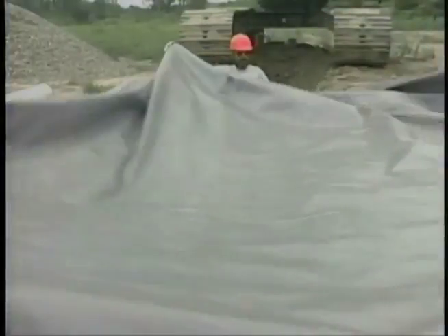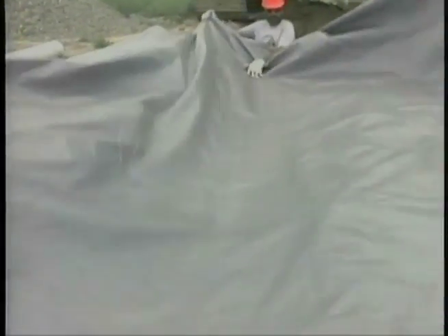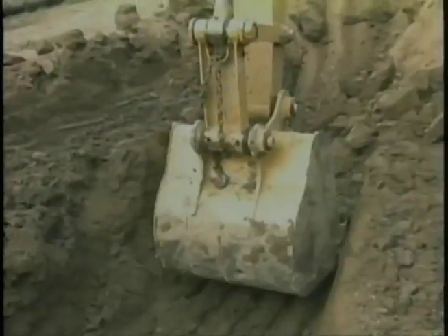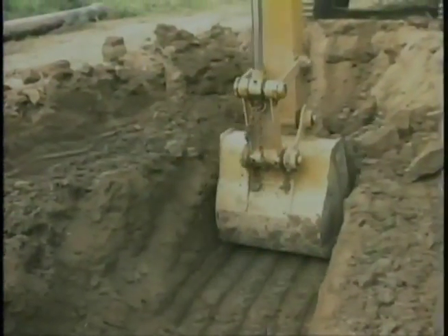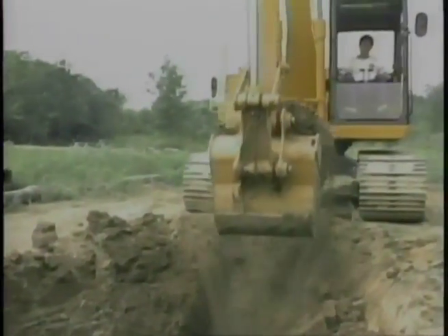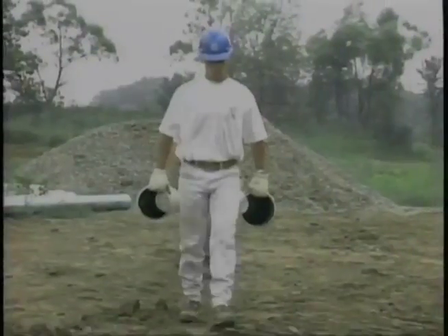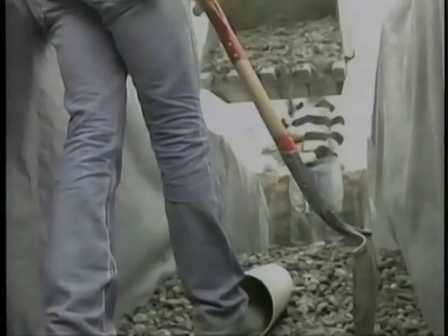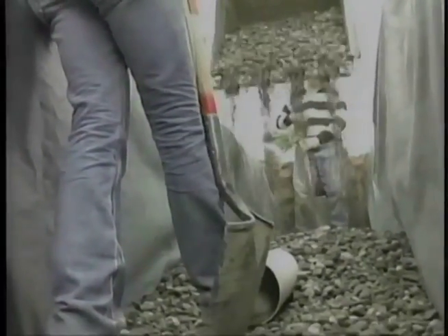A common design feature of installing perforated pipe uses a filter fabric and washed stone to envelop the walls of the excavation. When installing the filter and washed rock, the excavation must be dug deep enough to allow the fabric and bedding to be installed. These design features create a filtering system that prevents siltation and clogging of the perforations.